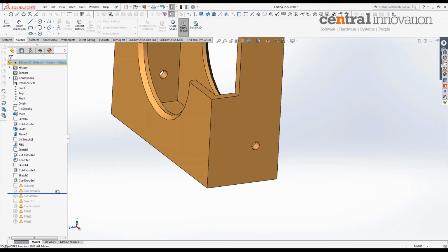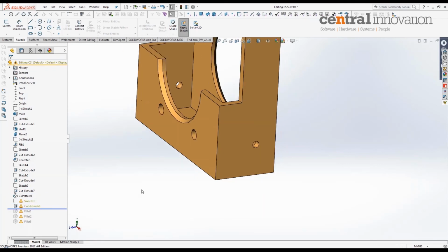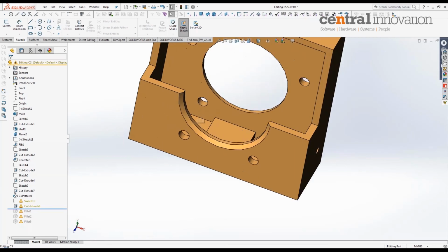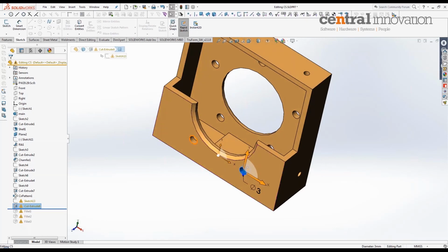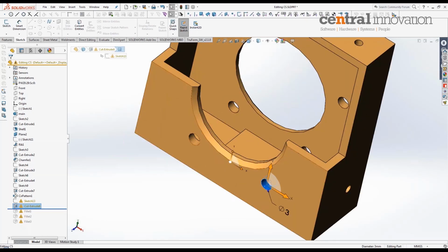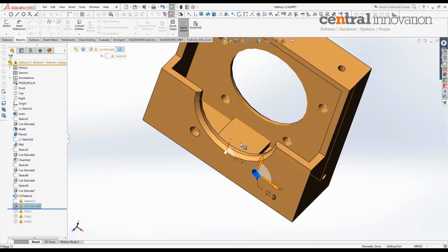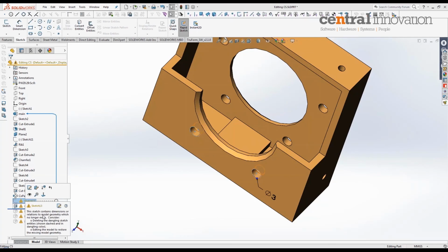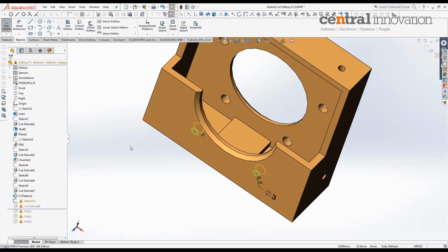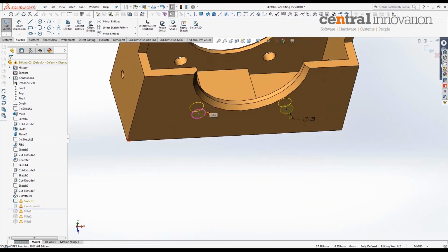So similarly, you could go further down, and my circular pattern seems to be okay. Yeah, so this extrude cut feature, these two seem to have a problem. Ideally what should happen is these circles should be aligned if you need to send a shaft through any apparatus. So I'm going to have a look at the sketch itself to understand what's wrong with it. It says again some of the sketch relations are dangling and I need to fix that. Go to edit sketch and it immediately shows me that one of the existing co-radial relations is dangling and also a concentric relation is dangling as well.